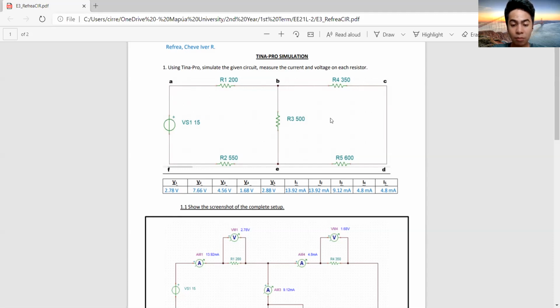Hence, any voltage drops around the loop must be equal to any voltage sources met along the way. When applying Kirchhoff's voltage law to a specific circuit, it is important that we pay special attention to the algebraic signs, positive or negative, of the voltage drops across elements and the EMF sources. Otherwise, our calculations may be wrong. So that is about KVL, or Kirchhoff's voltage law.